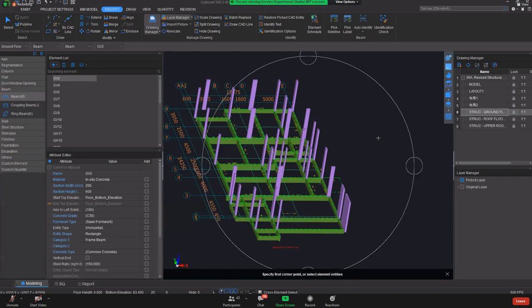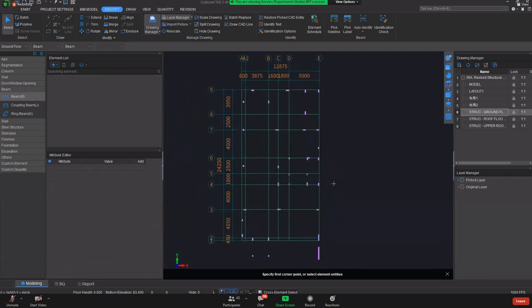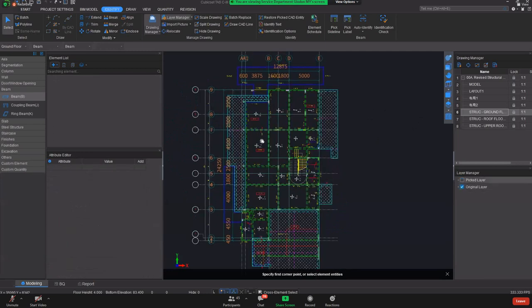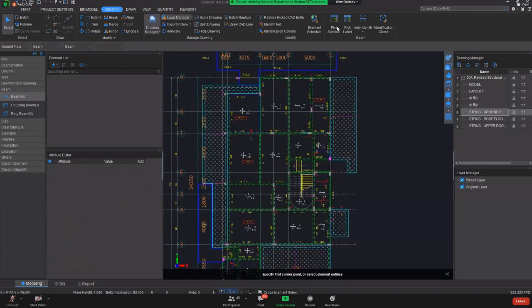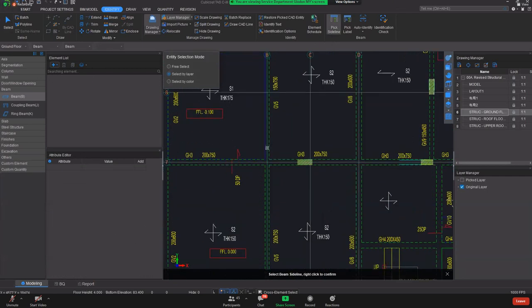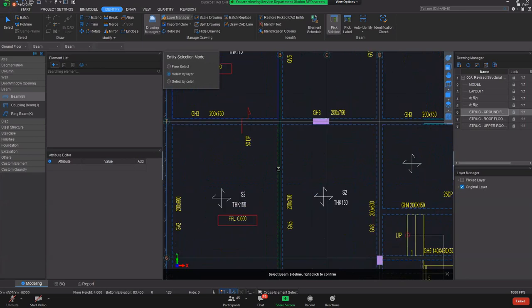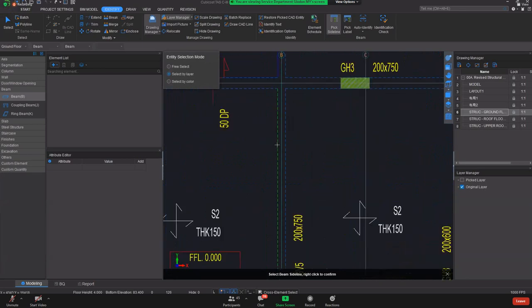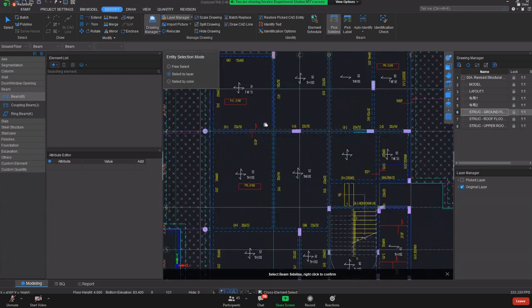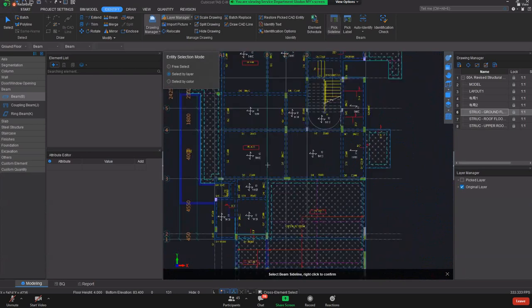Can I repeat again? Sure, no problem. One moment. Let me do it one more time. First, make sure we pick side line. I click on this dotted line. I can zoom in. I left click once. I don't right click first, because I have another green line I need to left click as well. To form it, you zoom out and check that all the beams are identified and selected, and then you right click.